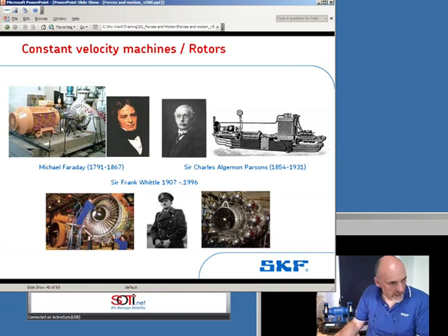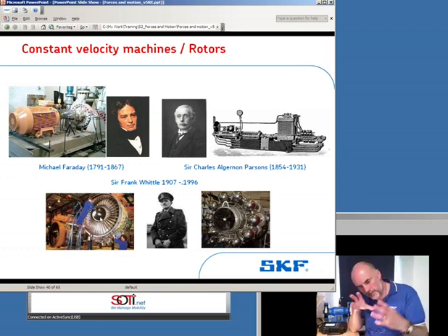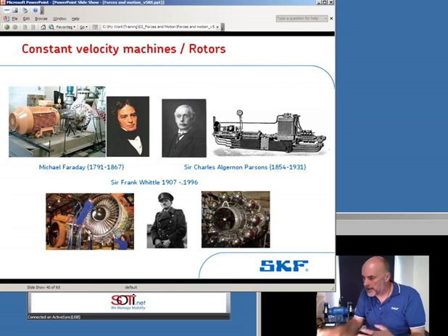And if you were to take an electric motor, steam turbine shaft, the impeller out of a gas turbine, and manufacturers actually do this, they'll put the rotor into a vacuum chamber, huge great things, suck out all the air, put the shaft on really frictionless bearings. They've taken the air out so there's no drag due to aerodynamic forces. This thing's running in a vacuum. If you run the shafts of any of these machines in a vacuum on specialized bearings, you will find they behave as constant velocity machines.